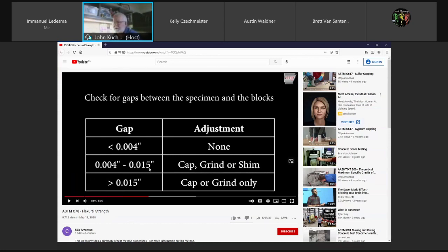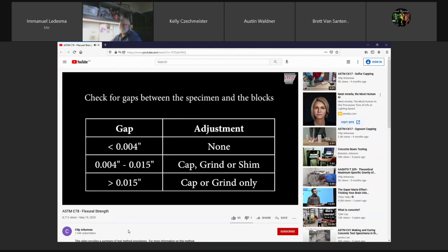Now ours are metric, these are imperial. And if it wasn't, you would grind it until you would. And you would use again a straight edge with a feeler gauge to make sure, because if you don't have total levelness across those contacts, you've got a high point. Your areas aren't the same. We basically shim it, and that's what they'll show here.